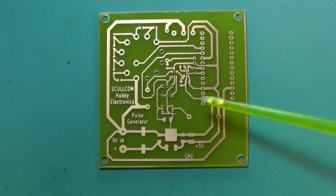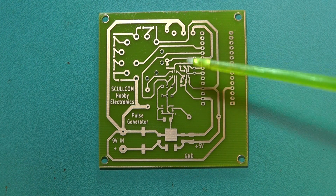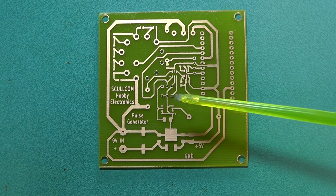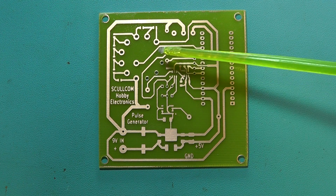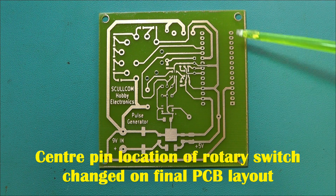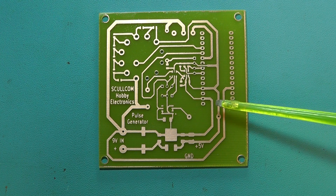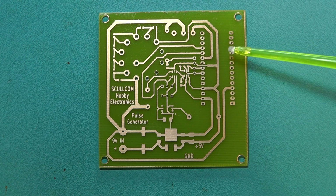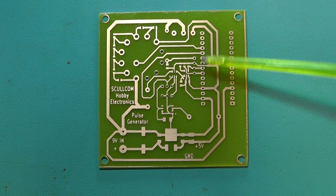All the other components on the board are mainly going to be surface mount resistors and capacitors, and I'll show you as I go along with that. The rotary switch is located in this area here, mounted through from the other side, and the Arduino Nano I'll be positioning it on the print side of the board. So I'll mount it here with the pins going through,